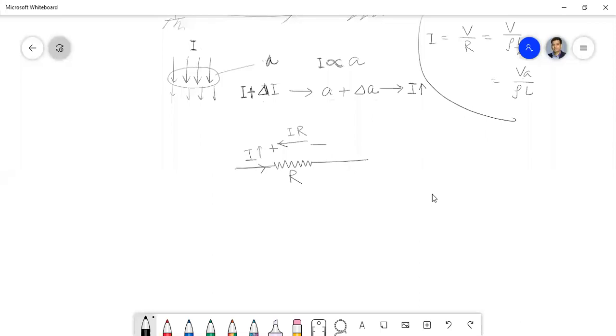The low pressure is maintained in the tube, and an arc is produced to give the light. To initiate this arc, almost 2 kilovolt or more, 2000 volt or more, is required. And that we somehow manage by using an inductive ballast and an automatic make-break switch called a starter.